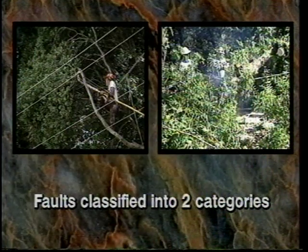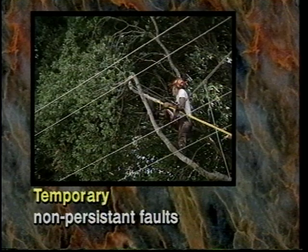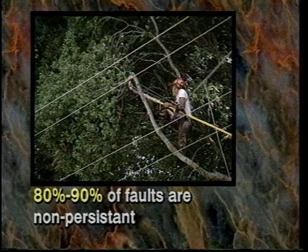Faults can be classified into two general categories: temporary and permanent. Temporary or non-persistent faults are those which will cease if the line is quickly de-energized. Permanent or persistent faults de-energize part of the system and require repair or replacement before re-energization can take place. Studies show that 80 to 90% of faults that occur on an overhead rural distribution system are non-persistent or temporary.